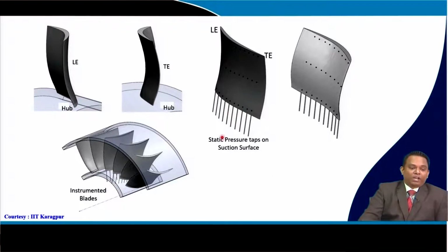Now here, if you look at these blades, what we were discussing about, say, the tandem bladed axial flow compressor, where we have our blade, that is a three-dimensional blade. Now if this is a three-dimensional blade, and we want to analyze what is happening with my flow physics, we need to go for testing. And for that testing, I cannot go with the linear cascade tunnel. I literally need to go with the annular cascade tunnel.